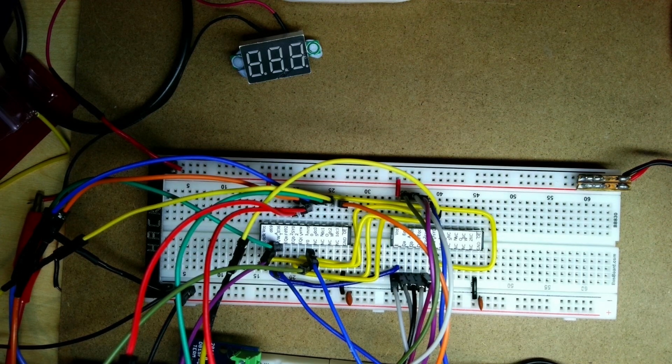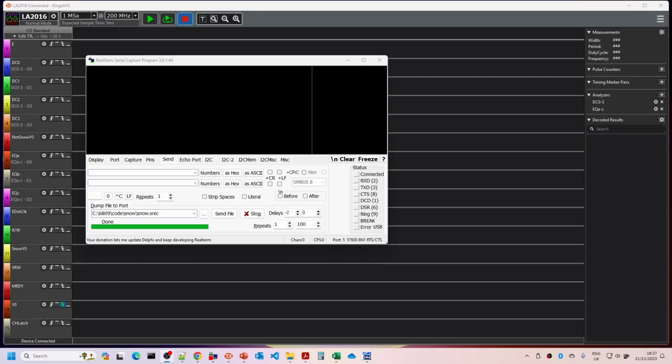And ultimately what we need to do next is to enable the MRDY logic on the main CPU clock, so that when we do try to extend the E signal, it will actually take the MRDY signal out of this circuit. So I'm just going to power on the NanoComp, and then we need to download the test program, because the issue here is that unless we're actually accessing the video RAM continuously, we won't actually see any of the conditions that we're looking for.